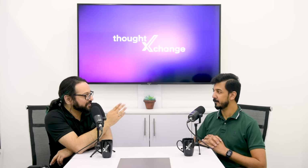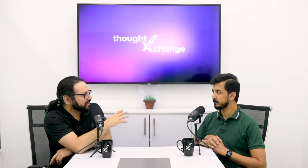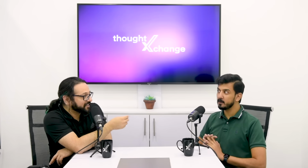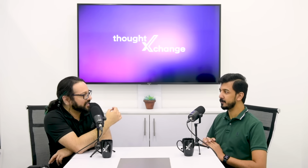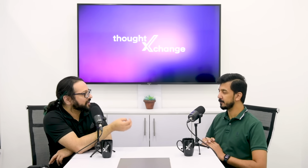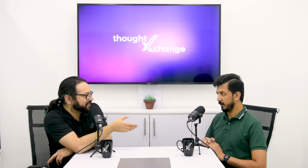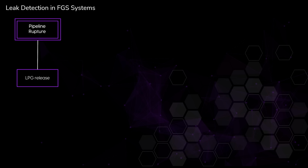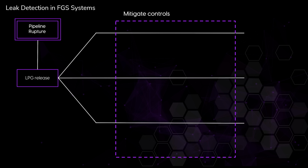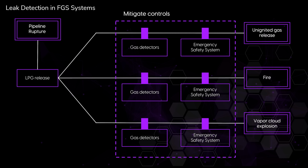And then if it goes into the environment, it's in a safe area or in a location where it cannot be ignited. It will be in an environment where ignition or some other sources are not available to make sure that spillage cannot create a greater environmental impact. It remains contained in that area. And in case there is some probability that you will have a leakage and there'll be some ignition source around, you need to shut down immediately. So that's where your safety systems would come in.